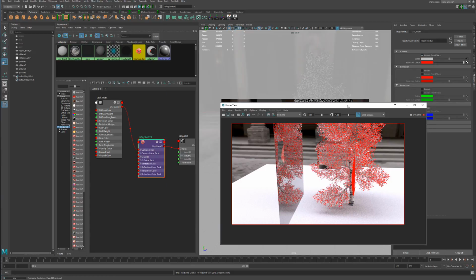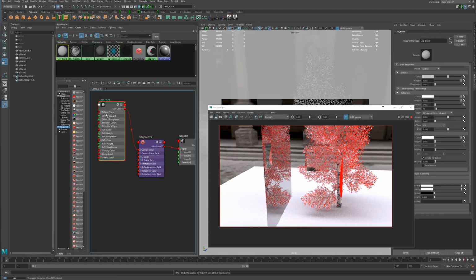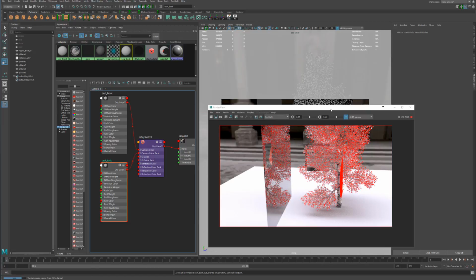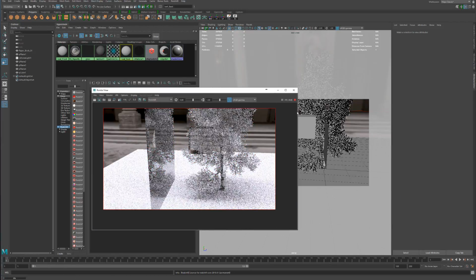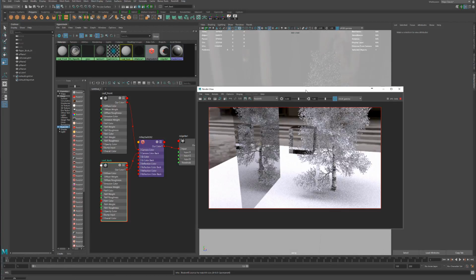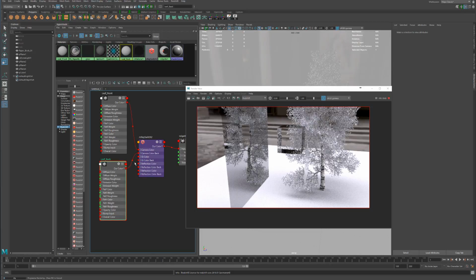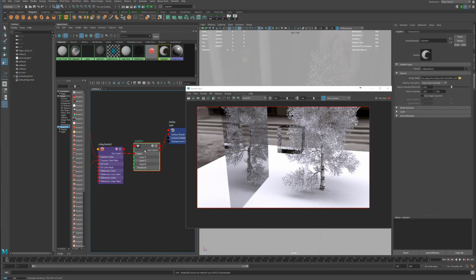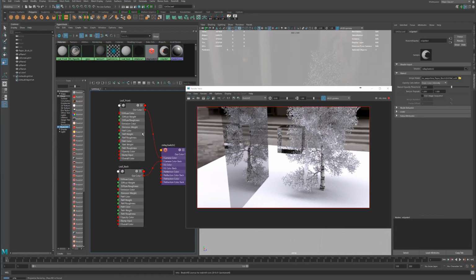And so now that we have that going, we're going to duplicate the front Redshift material, and we're going to paste this in. We're going to rename this to leaf back, and we're going to input this into the color back. And so what we have now, it'll be the same since it's a duplicate, but what we have now is two shaders feeding into the ray switch, which then feeds into the Redshift sprite to cut everything out, and eventually connects to our leaves and whatnot.